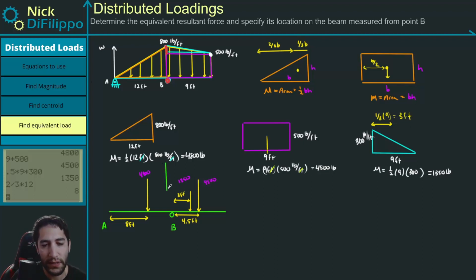So we'll have some force, well, let's say it's on this side of B. We don't know what it is, but we're going to say it's on this side of B. We're just taking a guess. If it's negative, it means it's on the other side, and it's going to be some distance of X away from B. So let me redraw this so we don't have that extra force, but we want to now condense everything into one force, and this right here is point B, and we want one force that's some distance X away from B, and this is going to be my resultant force.